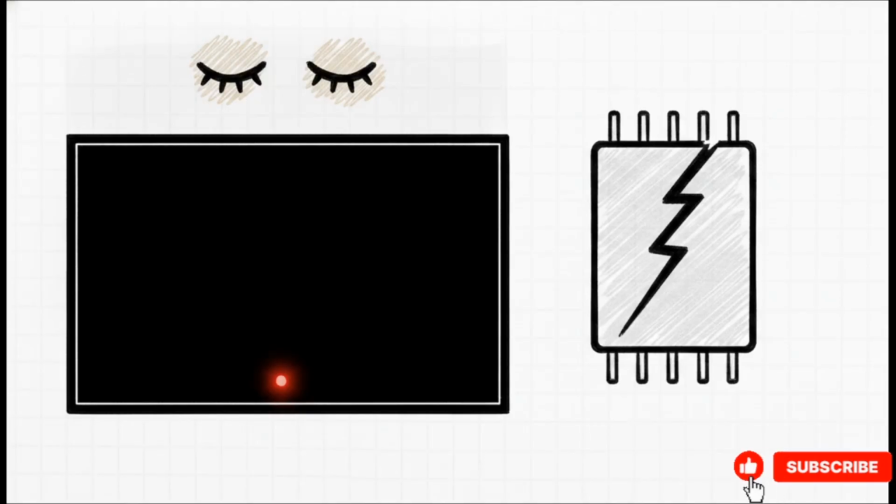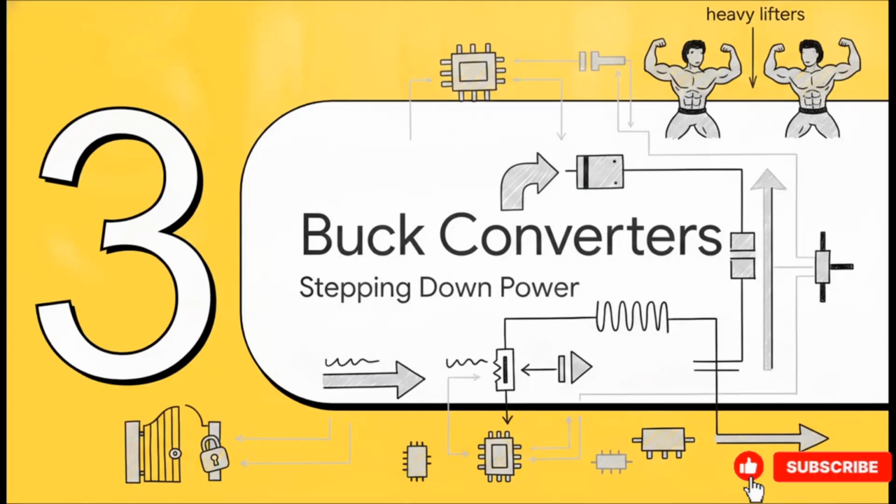But what happens when this gatekeeper breaks? Let's ground this engineering in reality for a second. The exact, super frustrating symptom of an LDO failure is a TV permanently trapped in standby mode. You press the power button, maybe that little red light flickers teasingly at you, but absolutely nothing else happens. This infuriating dead end is usually caused by an erroneous output voltage or maybe a failed internal pass resistor inside the LDO that effectively keeps the main board in a perpetual, unshakable state of sleep. No fun at all.